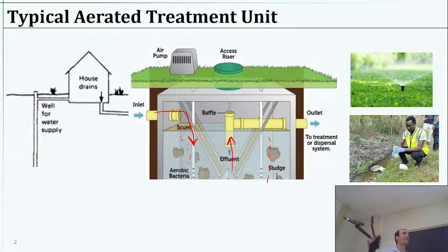He has one of these systems in his house, and he can tell when his neighbors are not chlorinating or run out of chlorine because of the smell. That probably also means their aerator is not functioning particularly well, as Evan probably knows. If the aerator is not functioning all the way, it's not getting enough air.